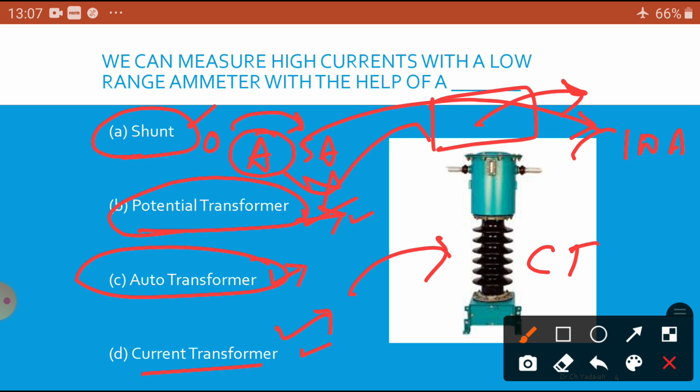So you can see a current transformer is nothing but a CT. How does the CT look? It looks like this one. This CT can be used in an 11 kV line or a 33 kV line, or we can use it up to a 132 kV line also. Sir, if I want 220 kV, then what? I can use that also, but increase the insulation from the base to this one. Once the voltage increases, the insulator gaps should be increased more and more. This is the live part, this is the earthed part, this is the line.